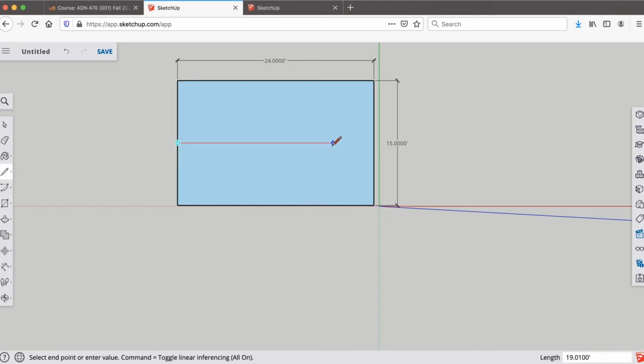So that being said, I can get a general idea by eye. If I click here, I can see it's a little shy of 19 inches. So let's say I want to make that 19 inches. I can just type 19 and the two little lines, which make the inch mark. I don't remember the name of those. Hit enter, and now that's going to be 19. From this point I could draw a line up. I don't know these other measurements down over here, but that's okay because I can figure them out very fast. Going back to the dimensions tool, bam, bam.